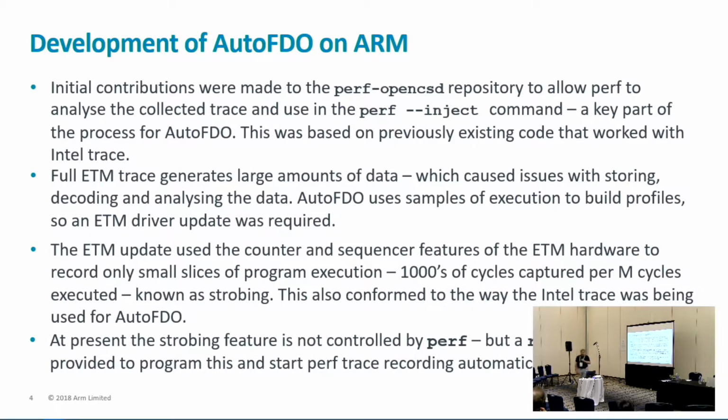So at present, the strobing feature is part of the ETM driver, but it's not controlled by perf. What we do is we have a record script that we provided as part of the demonstration system, and this will set up all the ETMs in the system and use perf to record the trace data automatically.